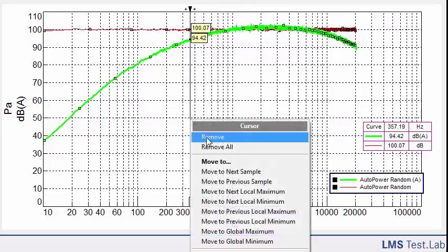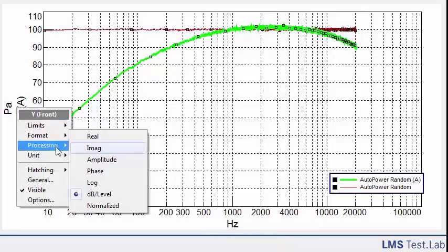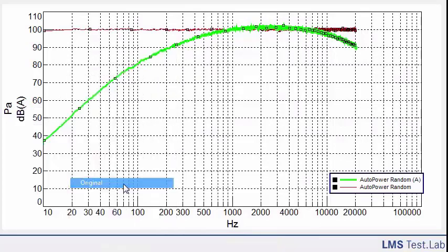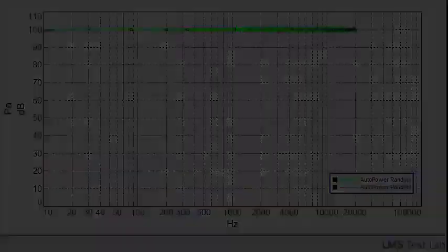So it's important to remember that if you're working on noise, for a human listener, you want to A-weight your microphone measurements to see how the amplitudes would actually be perceived by a human being and not just a microphone.